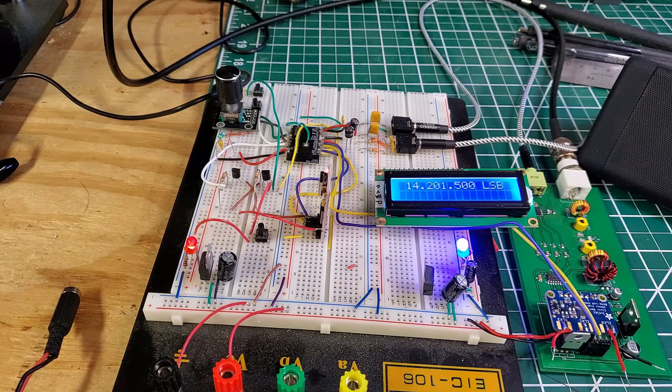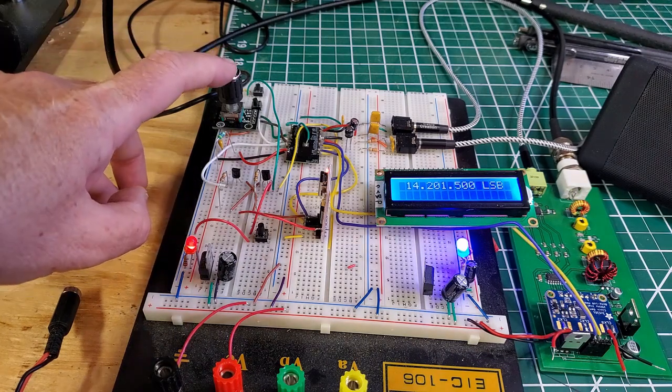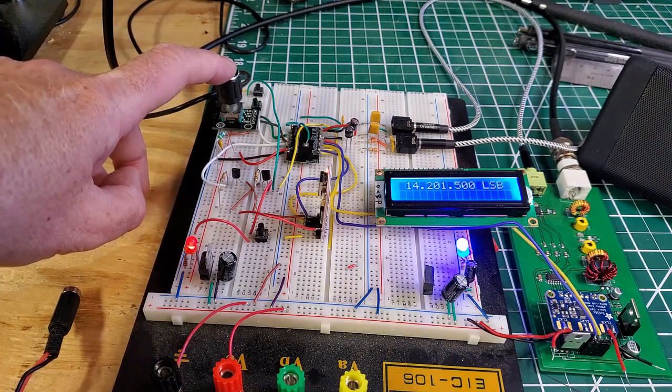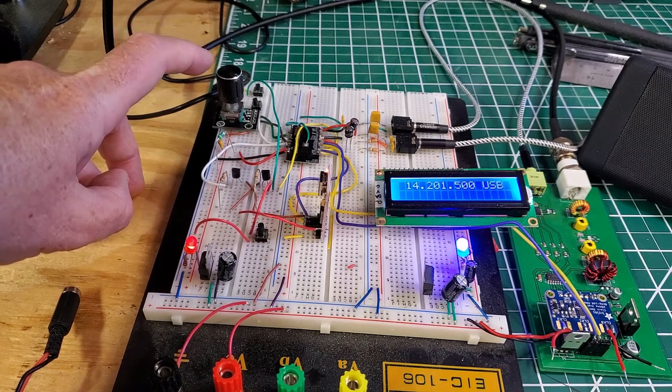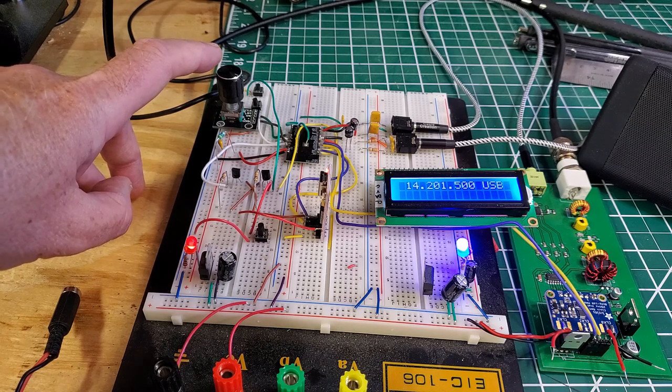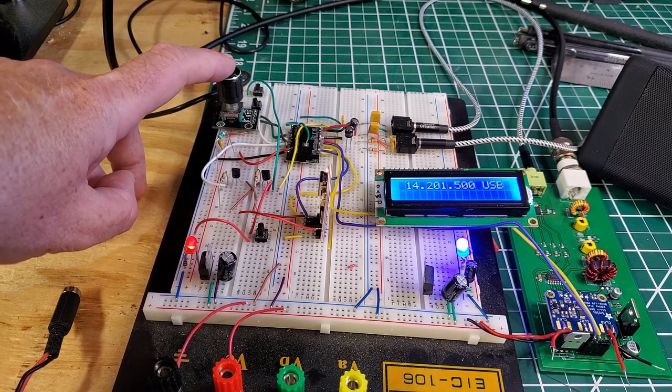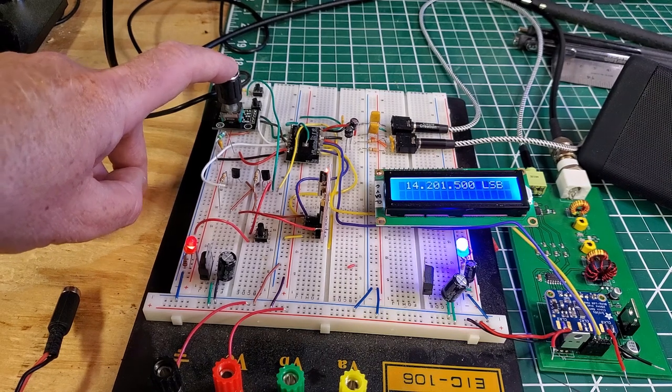And there you can hear the tone through there, so that's a 1500 hertz tone because it's on lower sideband. So let's change to upper sideband. We should get a greatly attenuated tone there. Now you can still hear the tone. The other sideband suppression isn't as good as I would have hoped, but let me be quiet and you can hear the difference between the two.